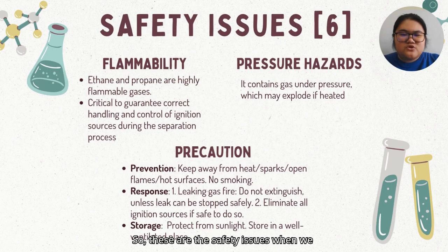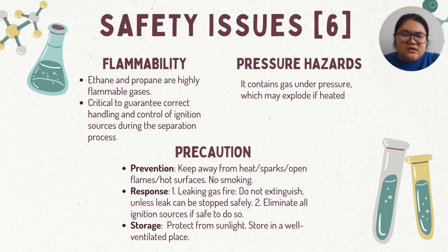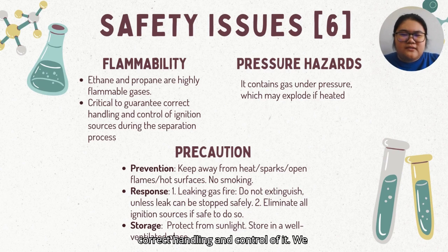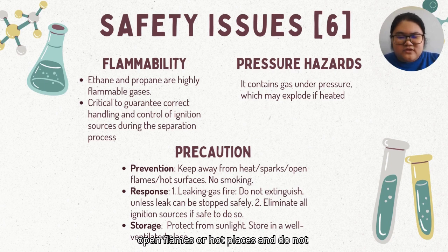So these are the safety issues when we are handling ethane and propane gases, as they are highly flammable gases. They also contain gas under pressure which may explode when heated. Therefore, it is critical to guarantee correct handling and control of them. We should keep them away from heat, sparks, open flames, or hot places, and not smoke when handling them.